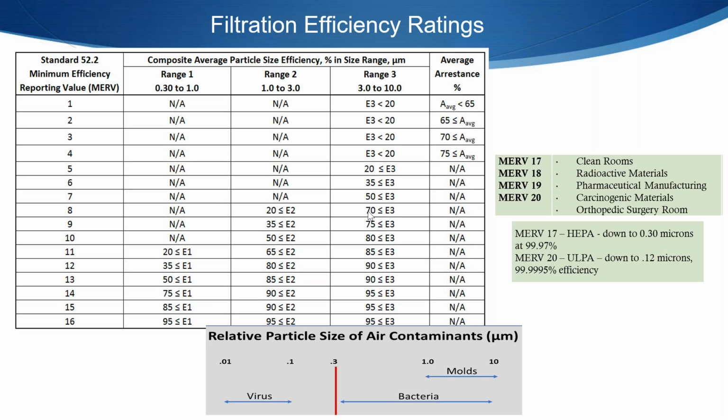When you're talking more along the lines of what we're seeing now, we're seeing an increase in MERV 13 filtration as a minimum filtration level in various locations. At very minimum, I see on the small commercial rooftop units is MERV 8 in most markets, MERV 7, MERV 8. So we're getting a 70% efficiency range in the 3 to 10.